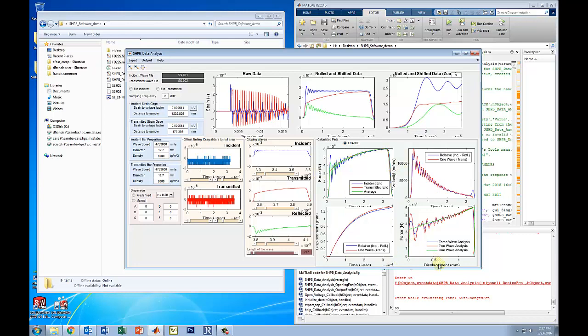In the end, you're going to be sending out force displacement, but the rest of the 3 plots are helpful to see whether or not you like the test as it stands, because the incident end and the transmitted end, the general curves ought to line up closely. The incident end is going to be much more noisy due to just the stress not being at equilibrium there, but the transmitted end will be much smoother.